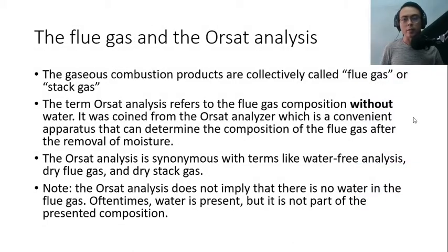So what is the flue gas? The gaseous combustion products or the product of the burner unit are called the flue gas or the stack gas. You can use those two terms interchangeably. Flue gas is just the same as stack gas. And so what is Orsat analysis? In one of our previous problems in the worksheet, you're given the water-free analysis of the product. That water-free analysis of the product is what we call here the Orsat analysis.